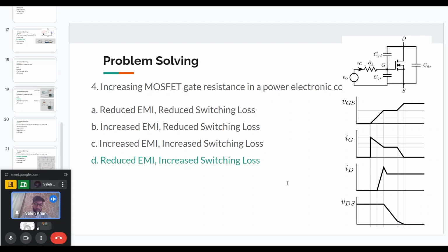Or if the switching is creating some noise and it is affecting the gate pulses, then you may want to increase the gate resistance slightly, keeping in mind whether the heatsink is enough. So it has limited capability for EMI.